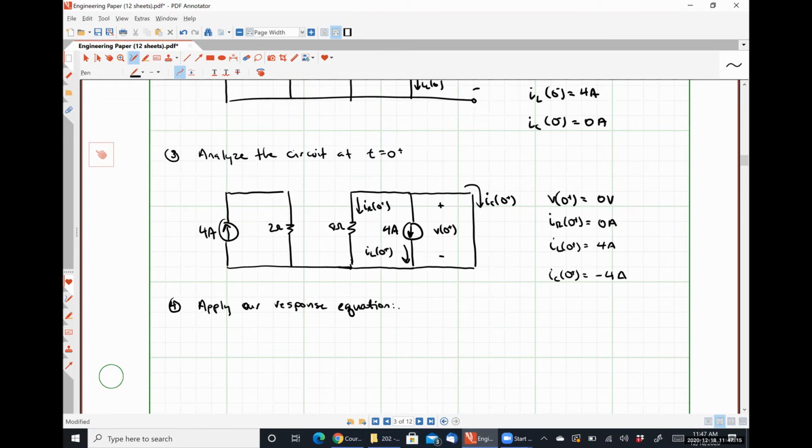So we know that because this is an underdamped system, V of t will be of the form B1 cosine omega d t plus B2 sine omega d t, sorry, I'm forgetting the t, e to the minus alpha t volts. At exactly t equals 0, what does this reduce to?